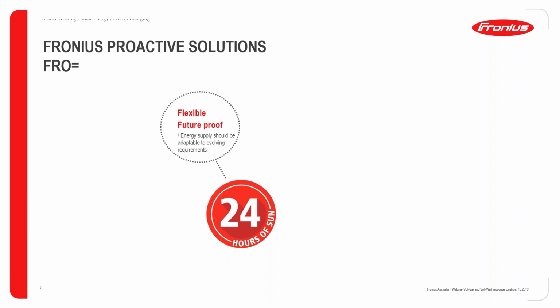We will see later how Fronius inverters are able to meet those demands. Fronius Galvo inverters, which we launched in 2013 or 14, can also meet the requirements of the Volt-VAR or Volt-Watt response modes. So that's one of the principles.